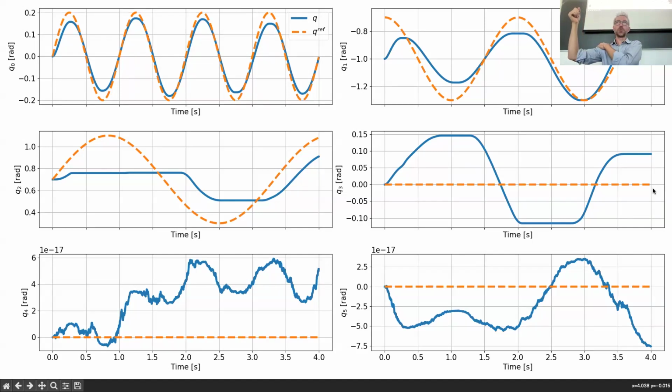When you generate torque at your shoulder, you're actually generating an acceleration also at the elbow, at the wrist, at all the joints of the chain. There is dynamic coupling. So even if the controller is not trying to move this joint, since it's trying to move the other joints, and there is this friction which is unmodeled, so the controller doesn't know it's there, this could result also in undesired motion in other joints. So probably I would say this is the coupling between joint 2 and joint 3.